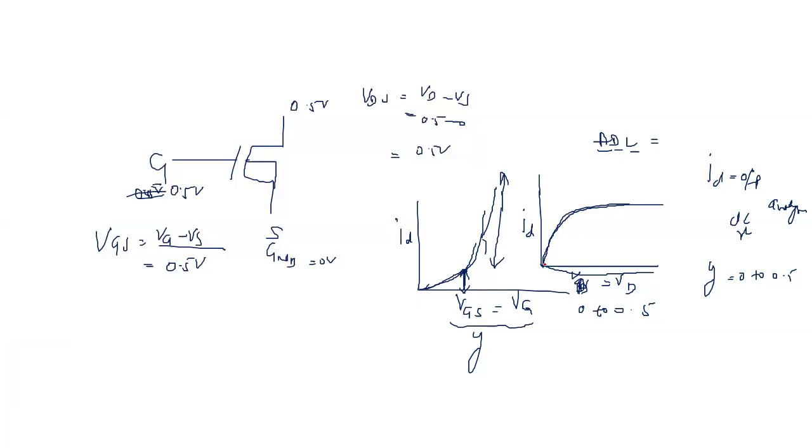Similarly, in output characteristics, till this voltage we have seen the linear increase in current. But after this linear increase, the current gets saturated. For all the students who are going to work in digital VLSI design, we all work in this domain only. Why? Because we say that in the whole process, the current is constant. However, actually the current is not constant. It is slightly increasing. But if you compare it with this part, it is almost constant.